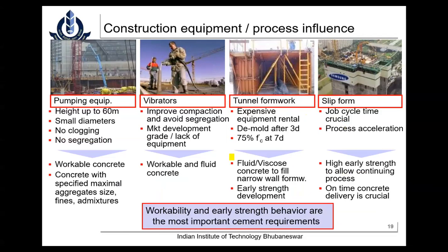Application one is talking about the workability and pumping of the concrete. There is another issue coming up, which is very crucial: the compatibility issue. Individual house builders never bother about all this; they simply mix something and pour it. But when you go for very big infrastructure or high-rise housing projects, this compatibility issue will definitely come. It is something like the cement manufacturer says my product is good, and the admixture manufacturer also says my product is good, but the problem arises when you use these two together.